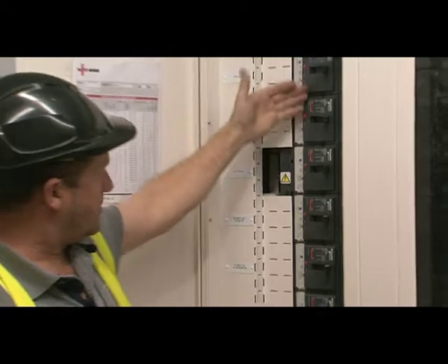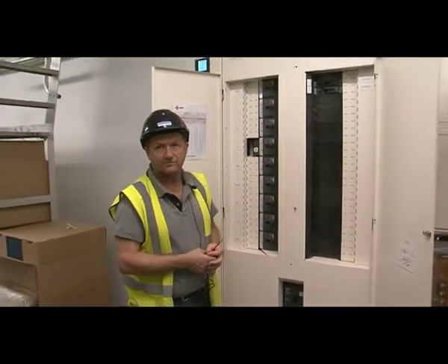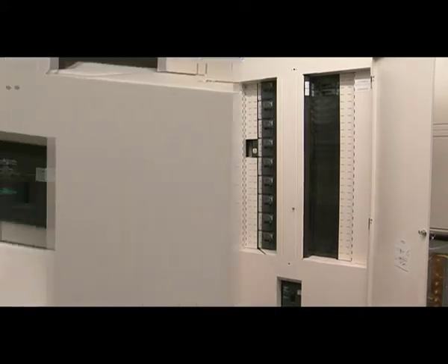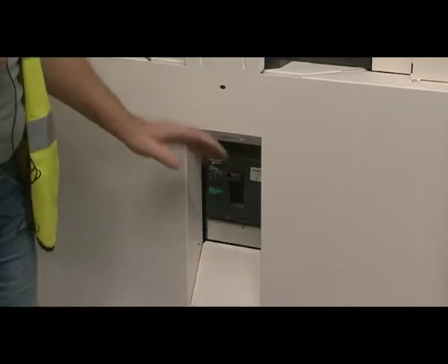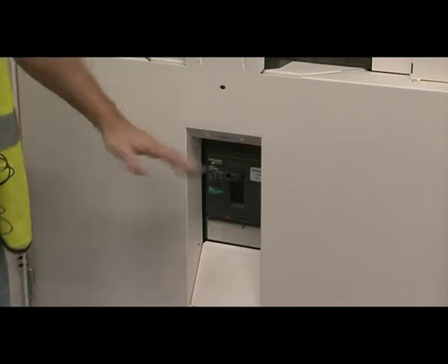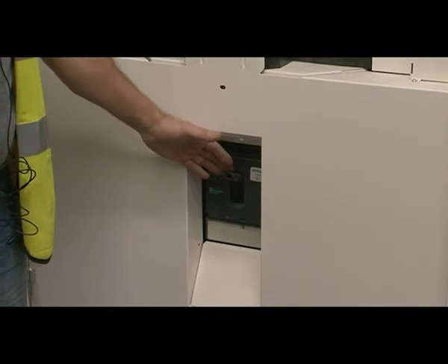Every one has its own breaker, and again they relate to distribution boards out in the field. In the event of full loss of power throughout the entire building, it's quite possible that the main breaker switch that feeds the entire panel may have tripped. It's an unlikely scenario, but it's well worth knowing about.